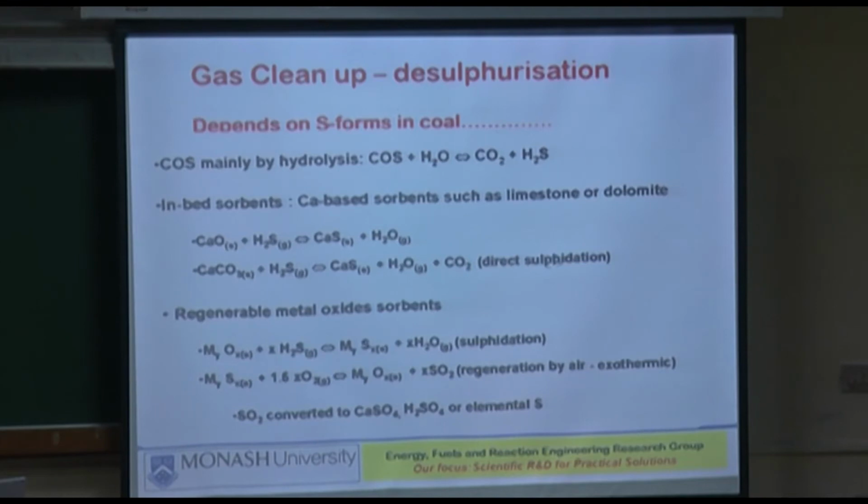So in the bed you can do it, and then whatever remains, which is a much smaller fraction, can be handled in a separate desulfurization bed if required, together with the fuel. Even though they come from different hoppers, eventually they get mixed closer to the entry point of the gasifier and then captured. The important thing is to ensure that they go to the bed together, so that in-bed capture is available.